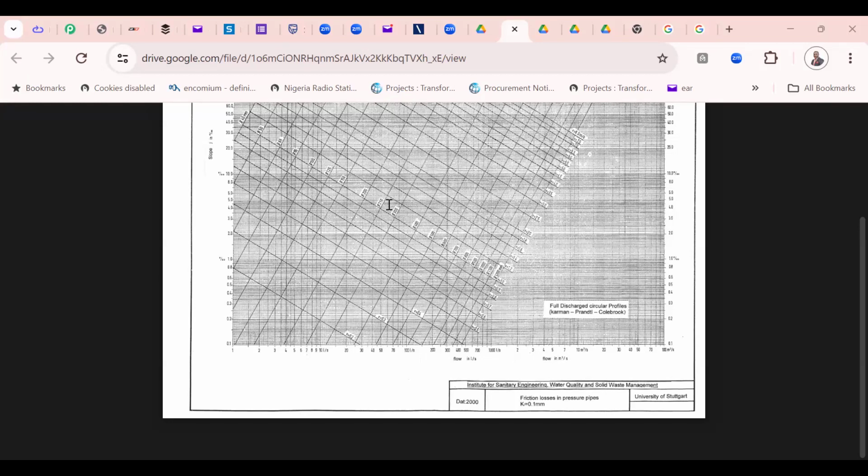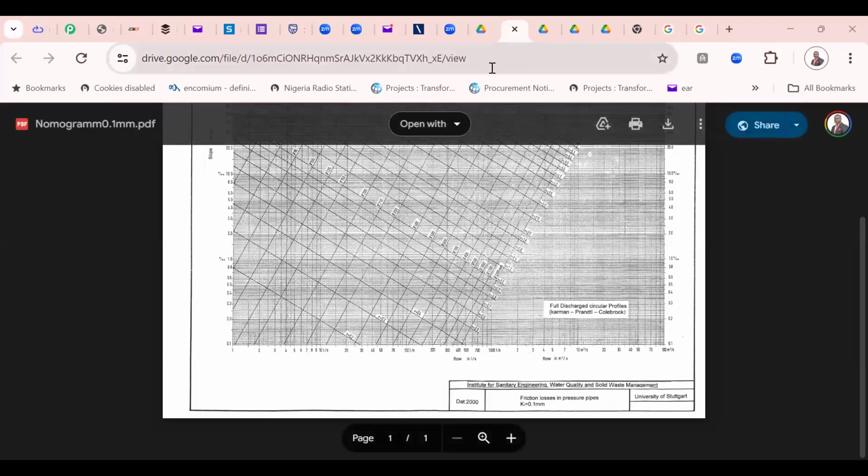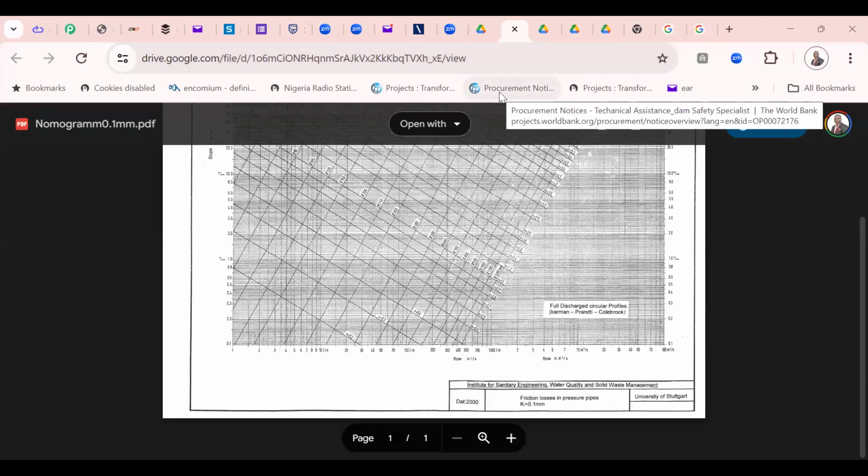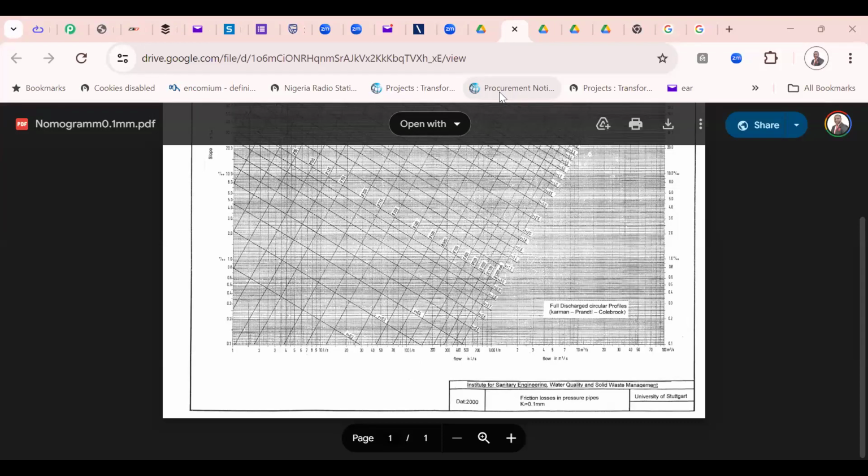The upper limit, yes. And those pipes are also sized based on what's available in the market. Market sizes, availability. So you don't get a 225, 7-inch pipe. If you go to the market, you might not see it. That's the standard. You can even choose 300 diameter? No, sir, you can't. It's higher. You will be a wasteful consultant.